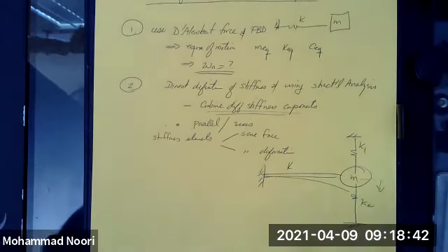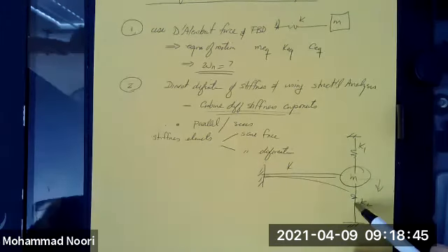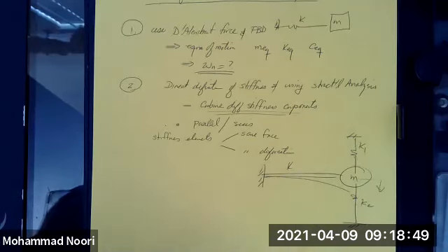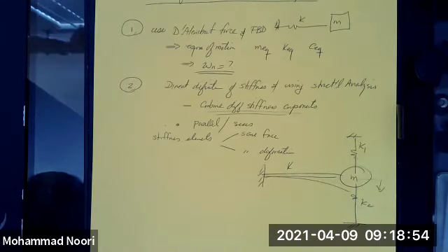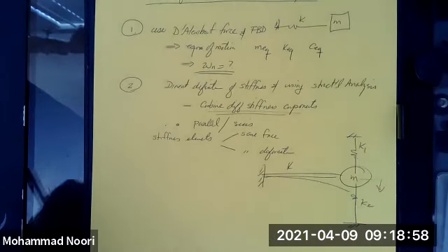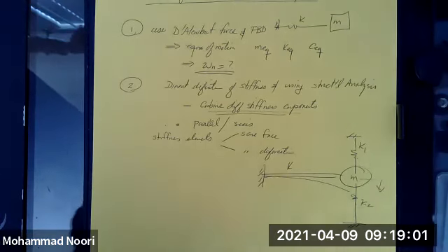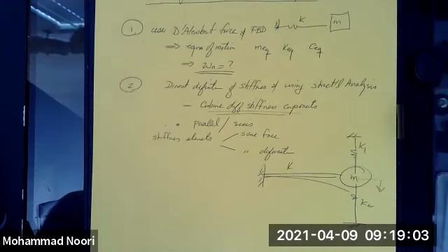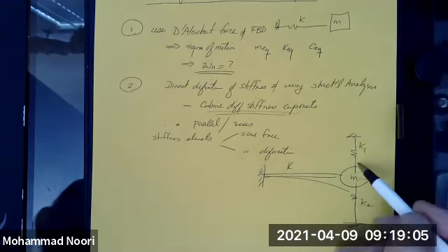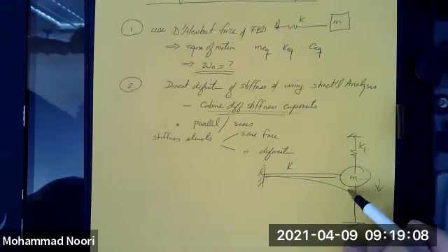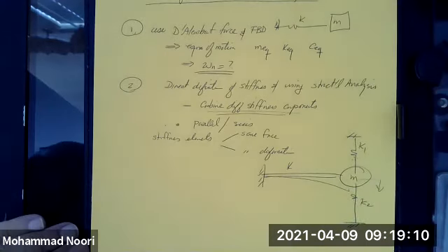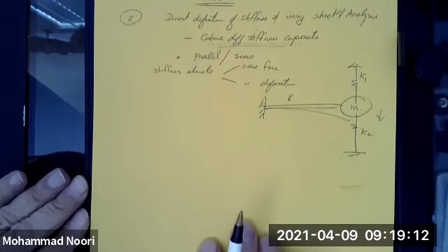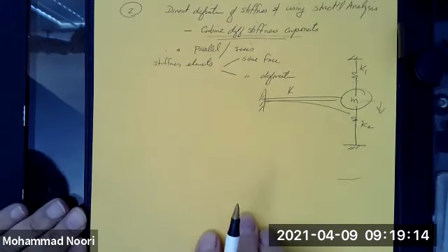So although these seem to be in series, they're not. In terms of the concept of a spring in series and parallel, which results in a different outcome for the total effect of these stiffnesses, these are not in series, they're in parallel. So it is important to be careful with this terminology of series and parallel.